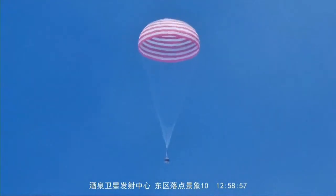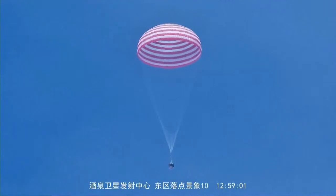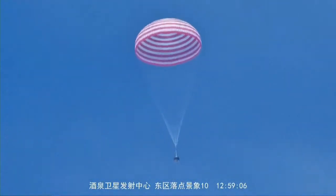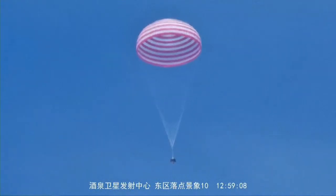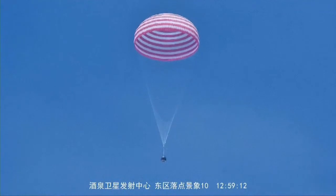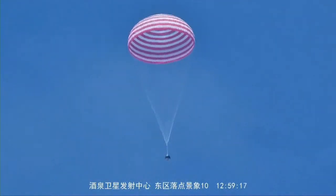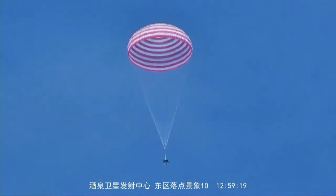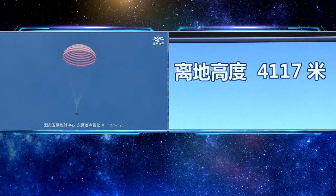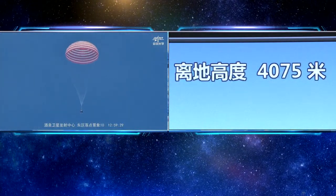Just on the bottom of our re-entry capsule, we have a device called a gamma ray altimeter. It will emit gamma rays to the ground, and with the reflection, it has a receiver to measure the time. So we can have a very precise measurement of the distance between the bottom and the ground. It will send signals to ignite the 4 rocket engines and slow down the vehicle to, as mentioned, less than 2 meters per second. Right, and that's automatic? Yeah, this is completely automatic.